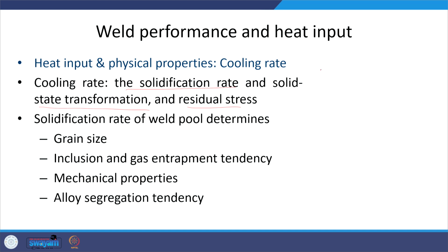As I have said, if the cooling rate is low, then the solidification time is long. That in turn will lead to a coarse grain structure and reduced mechanical properties. When the solidification rate is less and the solidification time is long due to the low cooling rate, that will affect the grain size, meaning a low cooling rate means a coarser grain size. It will also affect the inclusion and gas entrapment tendency. How? Let us see this.